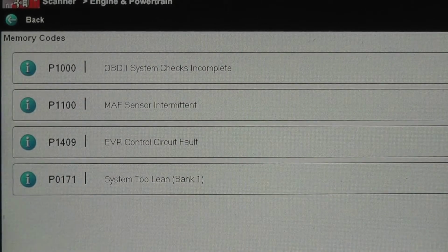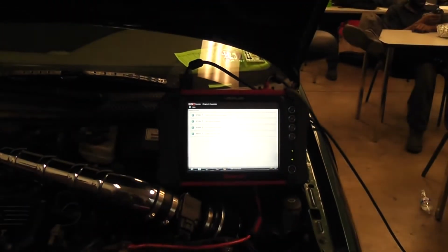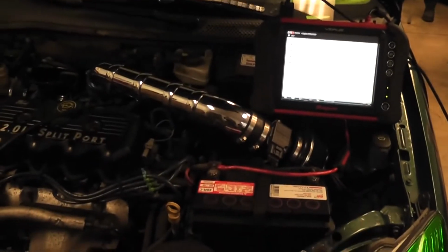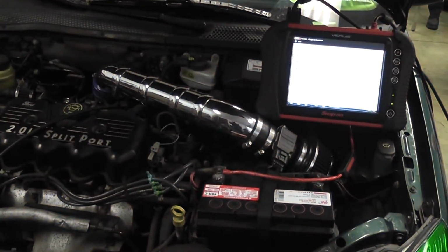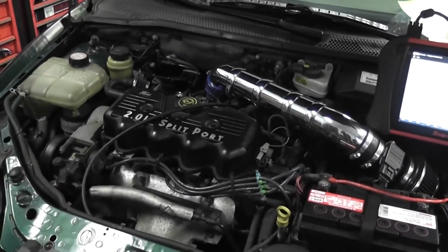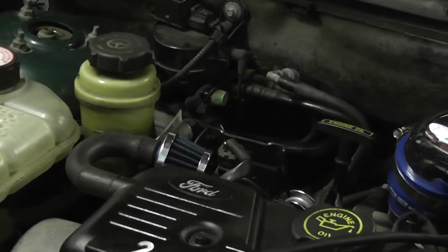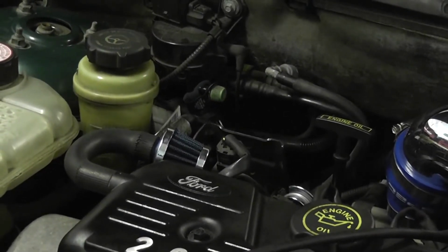One of the things that you guys in the field want to remember not to do is to put one of these intakes on these cars. And you see it's a, quote, cold air intake. It's that special intake manifold. And the big problem with this design is when you take the PCV system and you just put one of these little breathers on it and you basically take the PCV out of the loop, you are going to generate a lean exhaust code that you're not going to ever get rid of. So we're not going to worry about the lean exhaust code for this car.